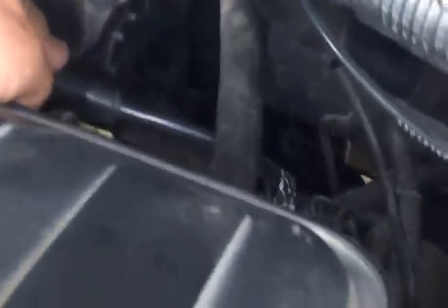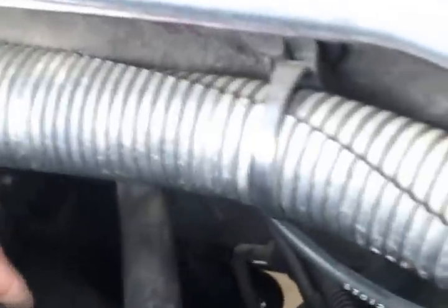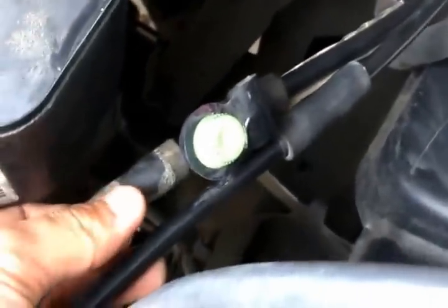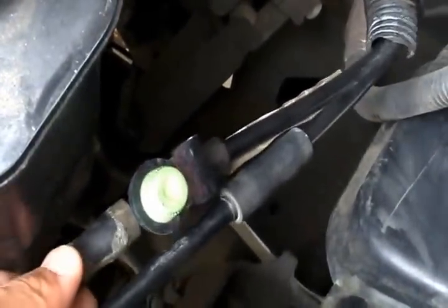And now I'm gonna take it to the throttle body port, which is right here. This upper hose right here runs to the throttle body, and I see that this throttle body also has a rubber hose attached to a plastic hose. From here, it looks in good condition. It's not brittle. I don't feel any cracks. And then the service port hose, this one actually runs all the way to the evap canister.